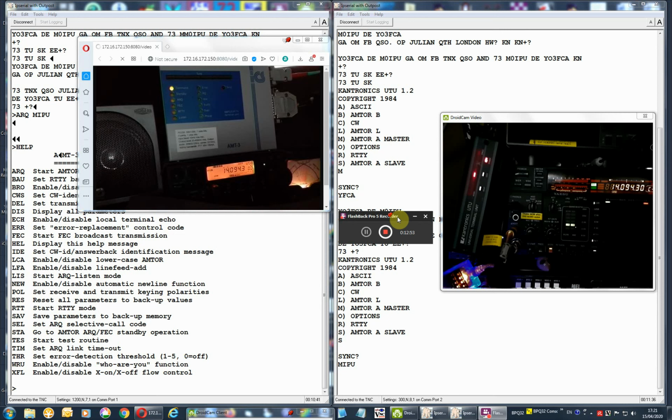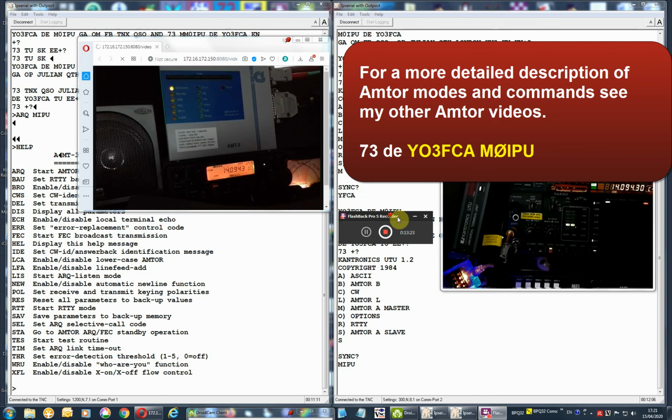If you have one ground for PTT and one ground for mic, you can split the ground into two. The audio out and the ground twisted, another ground with a PTT twisted again, and also for audio in, audio from the transceiver into the units, again another ground, and the audio in cable basically. I've realized it's quite good for avoiding RF going into these cables.